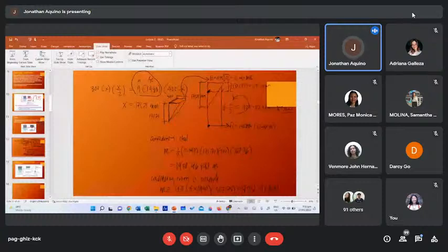It means if you consider the crushing strength, where the concrete fails, the moment it can carry is 1,938.96. While considering steel, it can only carry 898.95 kilonewton-meters.